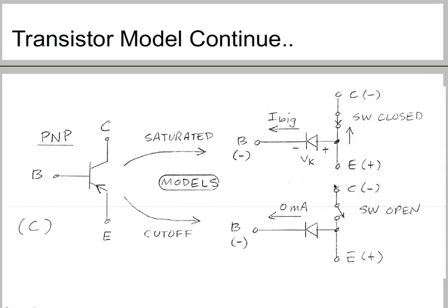If you suspect that the transistor is saturated, then analyze the circuit using the saturated transistor mode, then multiply the base current by 20. So 20 is the gain. If this value is greater than the current flowing through the collector lead, then the transistor is saturated. If it is not clear right now, we are going to see a couple of examples, and hopefully it will be clear.